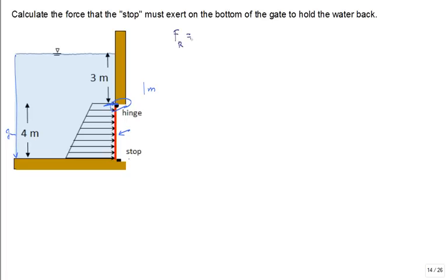Well, is it that I get the pressure at the centroid of the area? Yep. Where is the center? What is the depth at the center? Well, it's 2 meters down from the hinge, which is 5 meters down. So the pressure at the centroid of it is going to be rho g times 5 meters. I know I'm mixing symbols with numeric values, but instead of introducing another h, and h1, h2, h3, h4, I'll do it that way. That'll be the pressure down there, true?